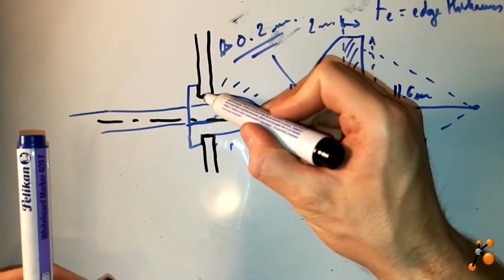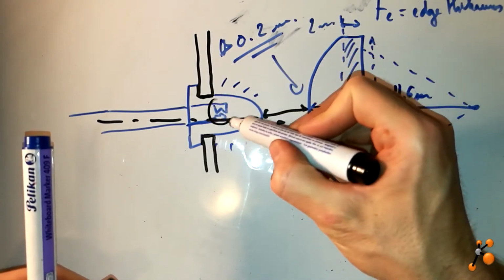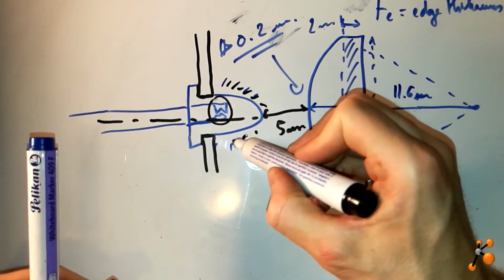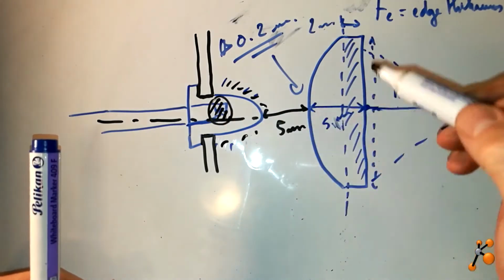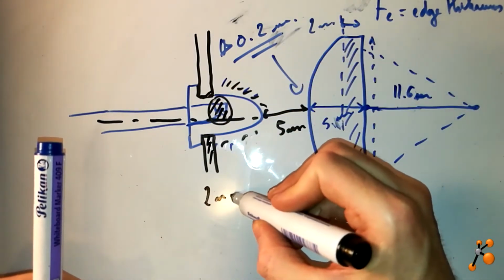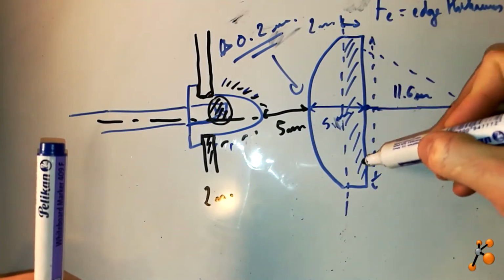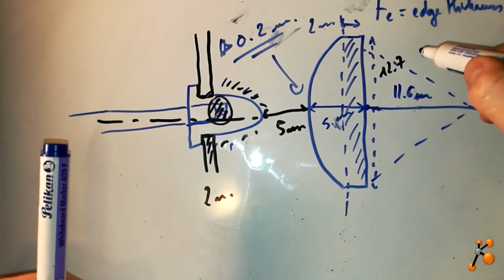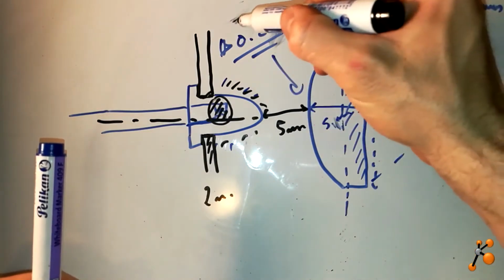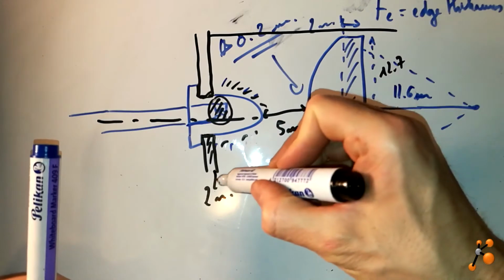This is more or less the flat part of the LEDs, and just before where you have the emission part of the LED. So it's better to put the wall here. The wall, I would like to put 2 millimeter wall. And then we know that this distance here, I told you, is 12.7. Okay? So you need to make a wall exactly 12.7.